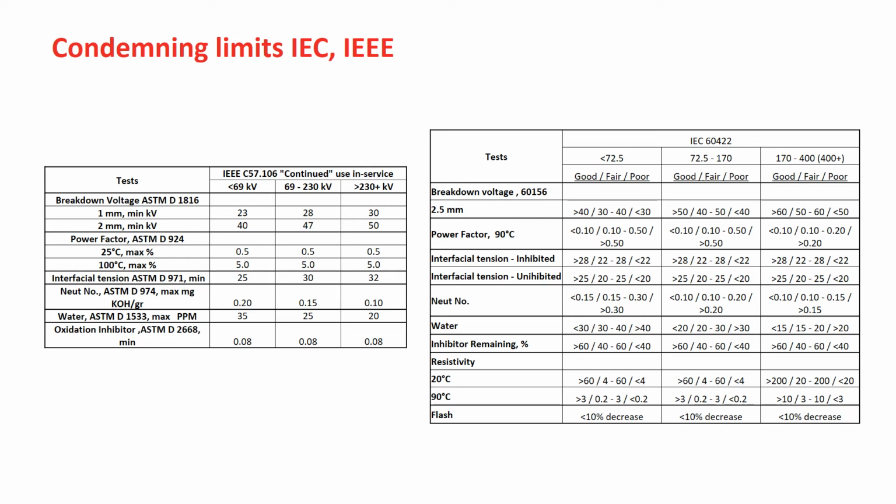Interfacial tension indicates how much of the non-polar molecules of the oil are changed to the polar hydrophilic molecules, and when measured over time, it reflects the oil's ability and eventual degradation. Every 1000 dynes per centimeter is equal to 1 Newton per meter.